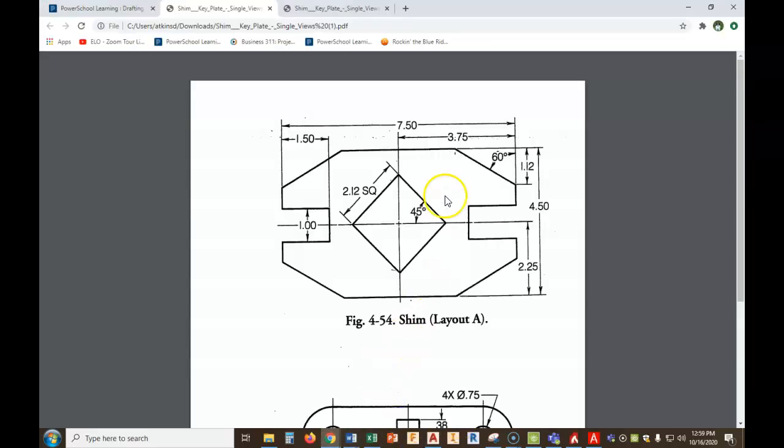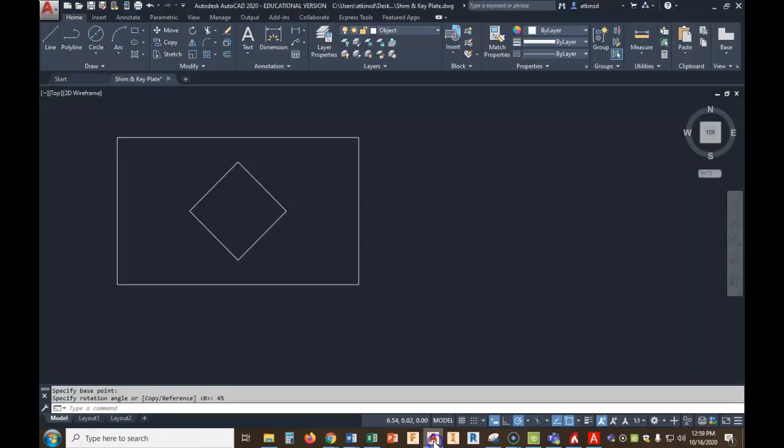So what's next? Well, next, let's put these little cutouts in the ends. Notice they're 1-inch cutouts on each end. 1 inch is tall. See my number here? And then how far in those cutouts go? We have to find our dimensions with our arrowheads. They go in 1.5 inches. Okay, so we can do that. So 1 inch by 1.5 inches.